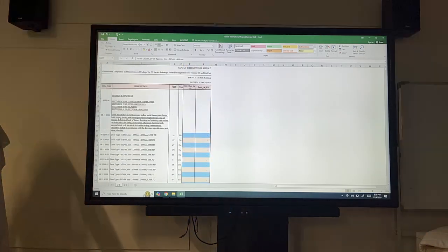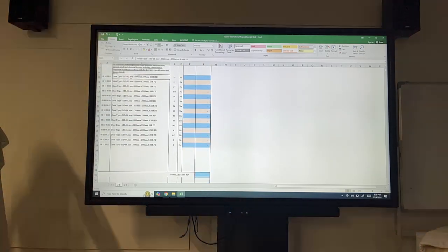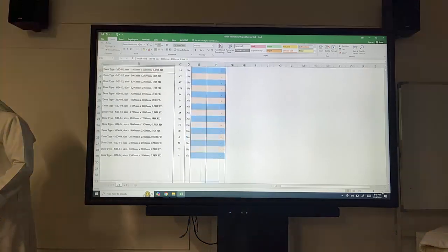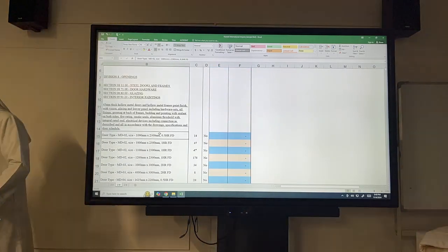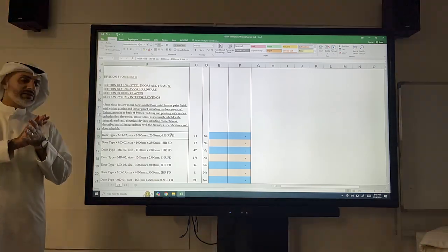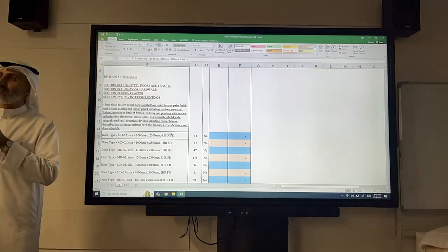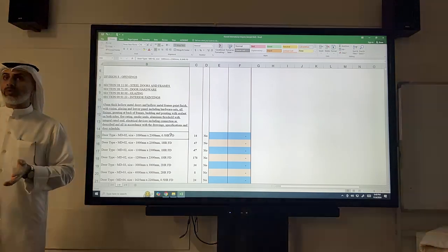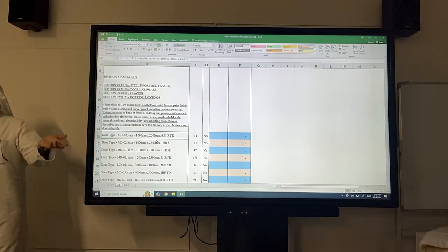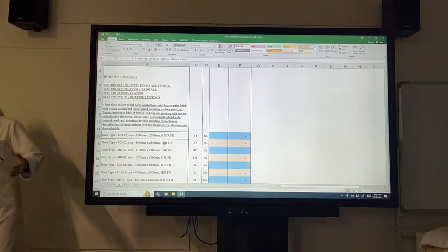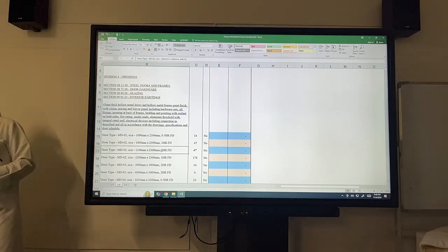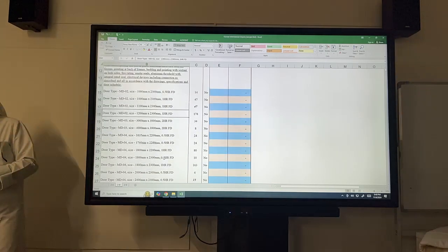So here you'll see door type, tag. I'll tell you this door only needs half an hour fire rating. It means if there's a fire, it doesn't need to hold the fire more than half an hour, but then it will break. Some doors, depending on how many people are inside and what's required, until the fire truck arrives, that's usually how you calculate it, and how long you need people to be safe there, 1 hour, 2 hours, and so on.